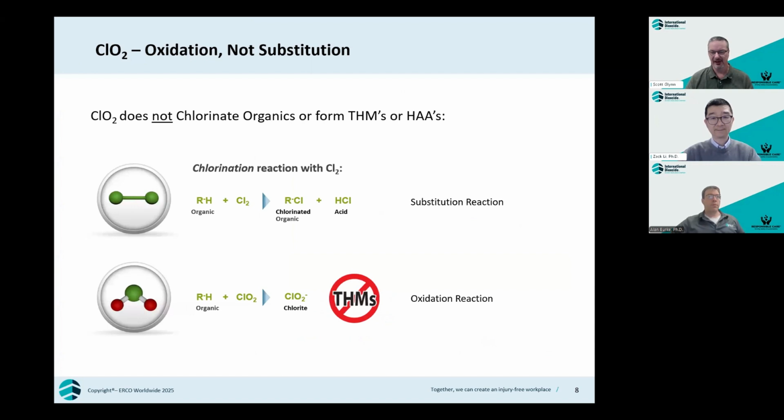Chlorine dioxide is a free radical, which simply means that it has an unpaired electron and wants to react with something that gives up an electron in a true oxidation reaction process. Therefore, chlorine dioxide functions as a highly selective oxidant when it reacts, which can lead to a much lower required dose to achieve the desired effect.